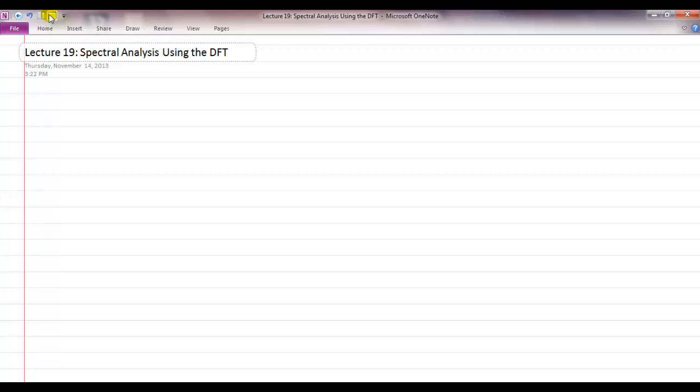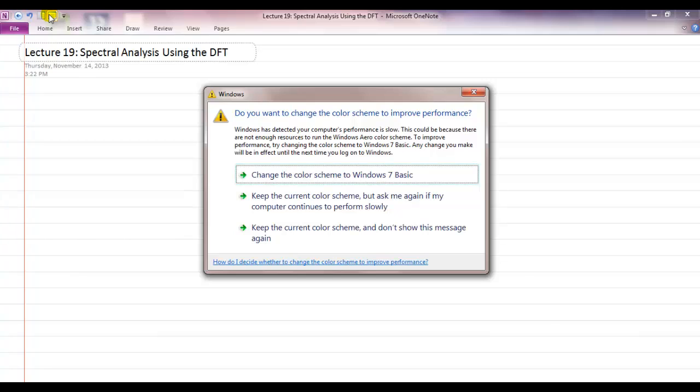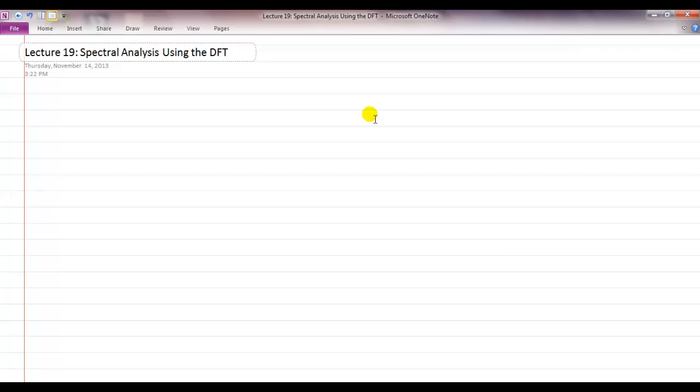look at, for example, why Wi-Fi signals are not working well in this region. What you can do is sample some RF bandwidth, for example, the bandwidth that the Wi-Fi signals transmit on, and you do their DFT, you try to figure out which frequencies are interfering with each other, and you perhaps set your Wi-Fi to a different place. That's just a consumer product kind of application.